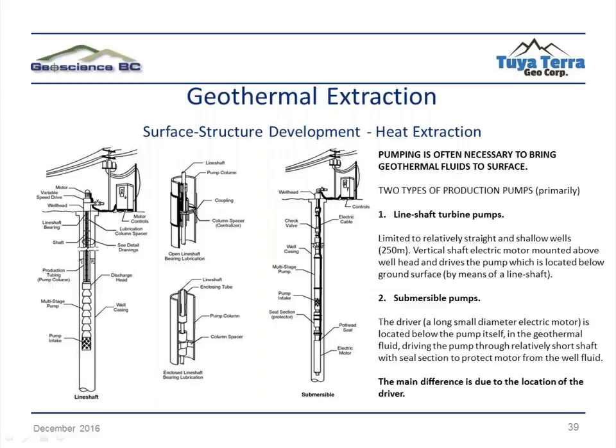The other thing that needs to be taken into consideration is that your well needs to be straight. You can see from the diagrams, for instance, the line shaft pump is a long series of mechanical parts, and your wells need to be straight in order for them to work effectively.